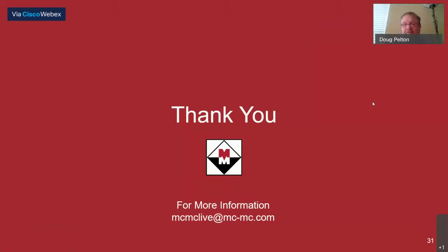No. Well, yeah. The statement is correct. There are 3 right now. There's also some legacy software that we don't really support anymore, and there's also Factory Talk View SE. But what he's talking about specifically is on-machine PanelView type products. So with the component product, it's Connected Components Workbench. PanelView Plus 6 and PanelView Plus 7 is Factory Talk View ME, and then it's Studio 5000 View Designer for the PanelView 5000. That's correct.